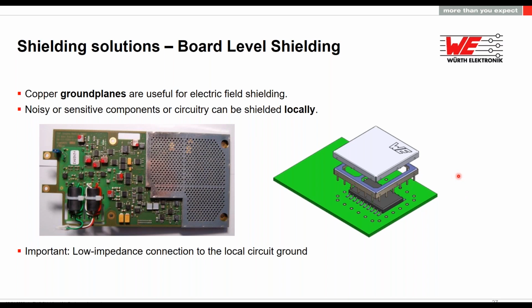These cabinets can help to prevent all the noise coming out of some part of our device, could be a noisy IC or some noisy part like traces and so on. Also, they can help protect parts that are sensitive. One really good example of where the cabinets are used a lot is in the protection of RF stages.